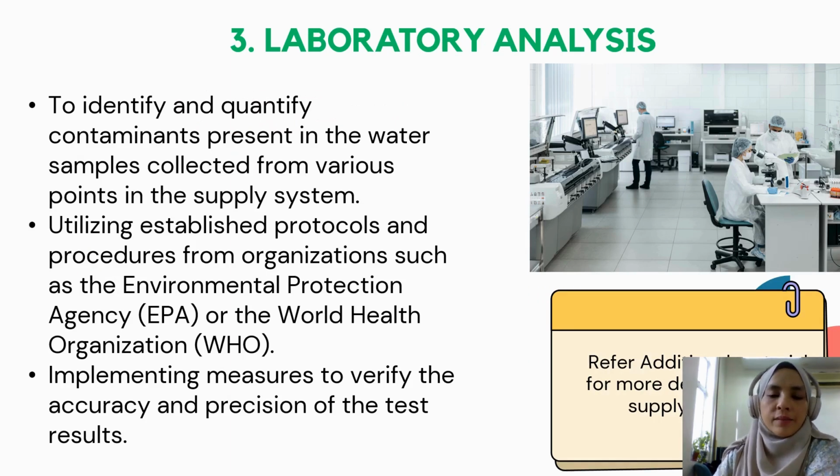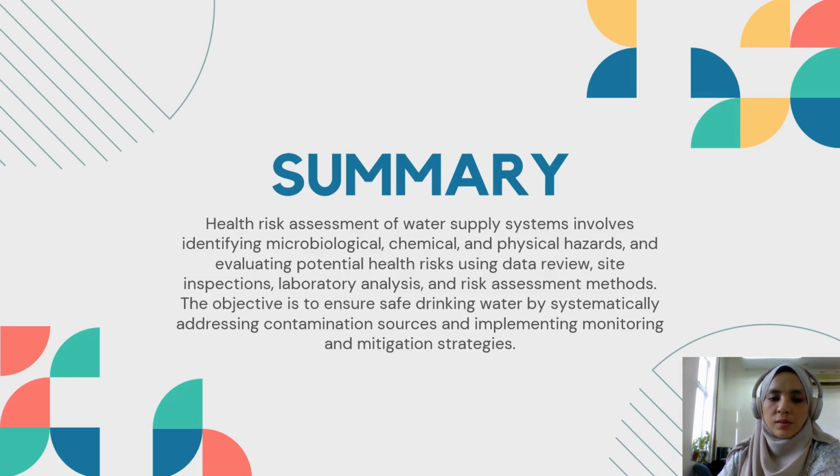Okay, after that, the laboratory analysis, to identify and quantify contaminants present in the water samples collected from various points in the supply system, utilizing established protocols and procedures from organizations such as EPA or WHO. Or in Malaysia, we can follow the National Drinking Water Quality Standards by the Ministry of Health. Then implementing measures to verify the accuracy and precision of the test results.